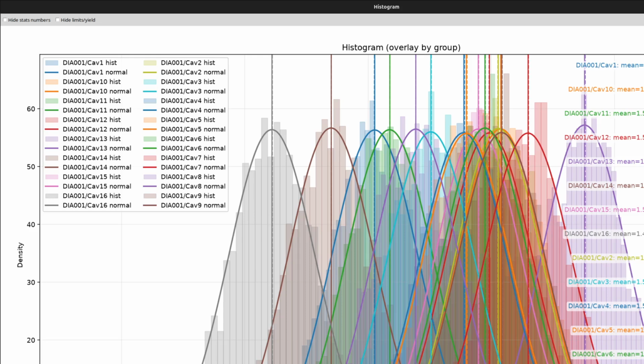So these all together would build their own larger standard distribution. But you can see that if we were to shift each of these medians to be right on top of each other, we've taken our standard distribution and cut it in half. So you can get quite a large tolerance or process capability gain just by looking at the statistics and then shifting those processes like that.